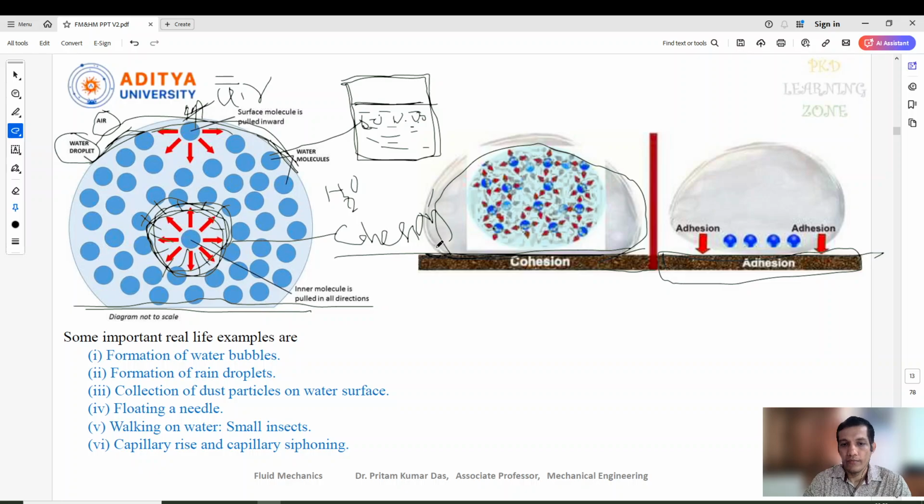or you can say it is able to extend its surface to this surface. So the forces between this liquid and this one can be called cohesive. Though the cohesive force acts between similar materials, similar liquids, here also the bonding, that means this material is able to attract this liquid, so there is an extension of that. So here also we can say there is some kind of contact angle between this material and that material. That is a different concept of hydrophobic and hydrophilic, which we won't discuss now. This is hydrophobic and hydrophilic nature.